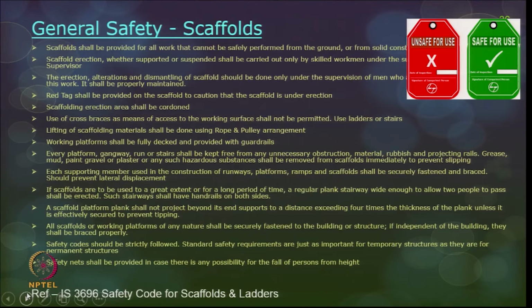General safety, again a recap on the scaffolds that we have talked about so far. Scaffolds shall be provided for all work that cannot be safely performed on the ground or from solid construction works. So, scaffold erection, whether suspended or supported, shall be carried out only by skilled workmen or by a competent authority under the guidance of a supervisor.